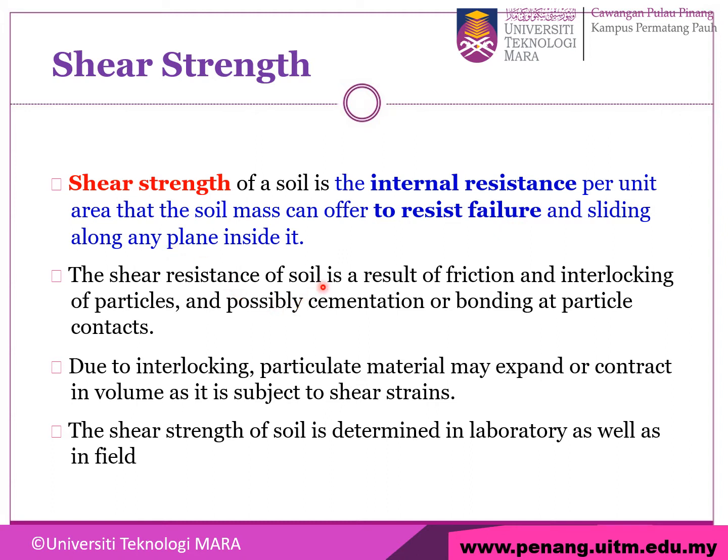The shear resistance of soil is a result of friction and interlocking of particles, and possibly cementation or bonding at particle contacts. Due to interlocking, particulate material may expand or contract in volume as it is subjected to shear strain. The shear strength of soil is determined in the laboratory as well as in the field.